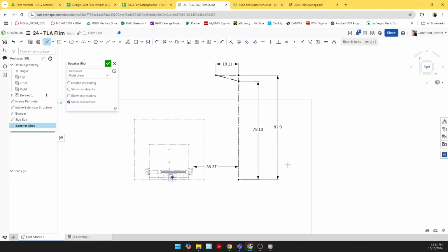What I'm also going to do here is another one. I'm pretty much going to copy that geometry again, and I'm going to make equality constraints. This is equal to this. This is equal to this. This is equal to this. This is equal to this. And last thing, these two are parallel.